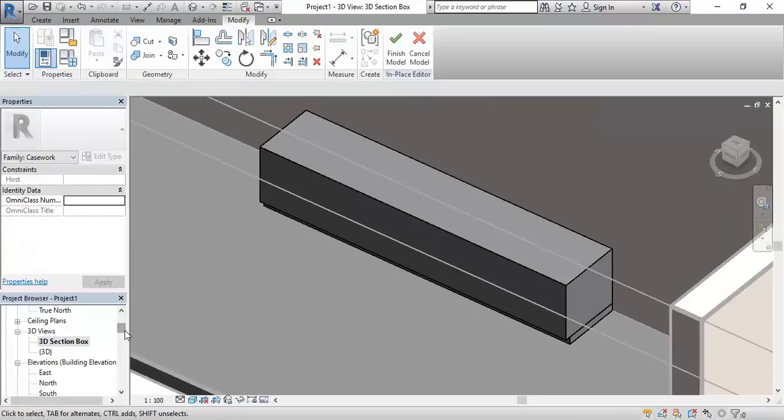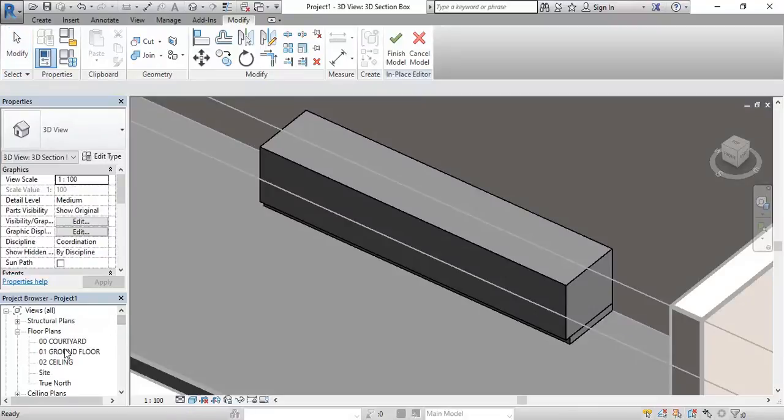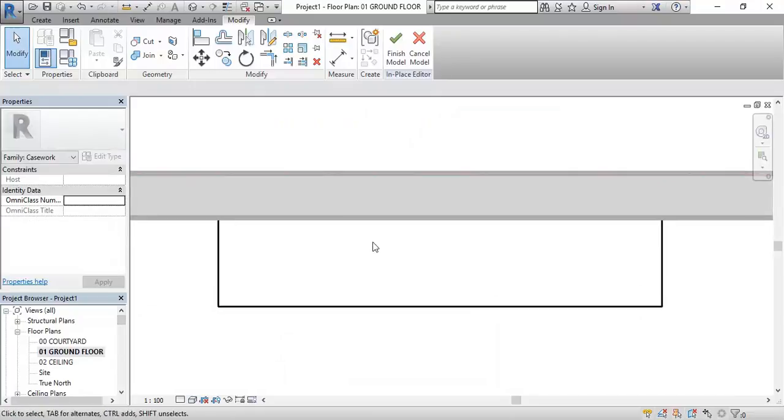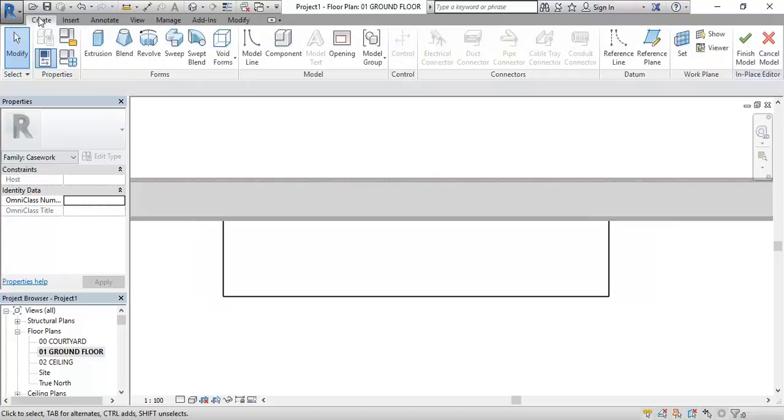So if it's a suspended one, just change the start. Yeah, exactly. And it's going to be just suspended. That's right, exactly. Mount it to the walls, fine. So now I want to put the bench top on. So back to the Create tab, I'll make another extrusion.